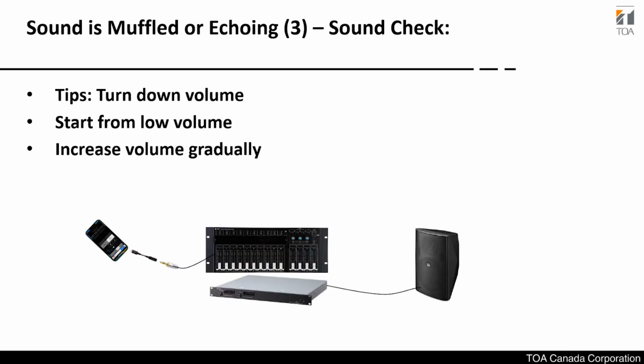So firstly, connect the smartphone to the mixer, and try to turn down the volume when you begin to do the sound adjustment or measurement. Start from a lower volume in case a sudden sound or noise comes up from the system, and increase the volume gradually.